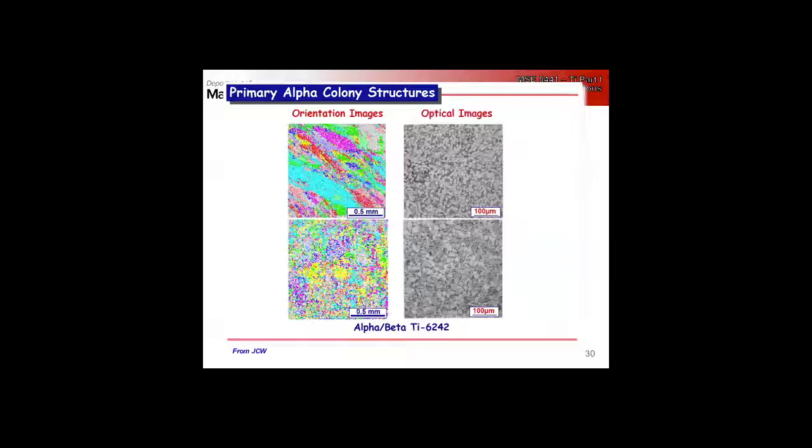But in a normal polycrystal, it's only going to propagate a short distance before it meets a different grain. Now we have to deal with tortuosity of the crack path. Here, all we need is a region that is well aligned for plasticity, a large microtextured region, next to a region that isn't, to nucleate. Then when propagation occurs, it can propagate really readily across this entire region. And if we look at the scale here, this is 0.5 millimeter. So now we've got an easy crack propagation path on the order of millimeters in our sample.